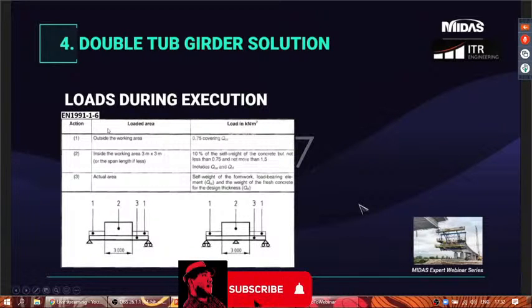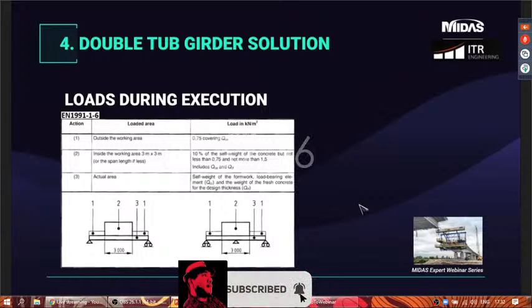In this third model, phases of execution will be analyzed. This kind of analysis is crucial for bridges, since the way you plan to build a bridge can change in a significant way the resultant stresses in the elements. A delicate stage for composite bridges is the casting of the slab. In this phase, the deck is only metallic, so we can have various issues that will be ignored without studying the structure step by step, for example, the buckling problem previously analyzed.